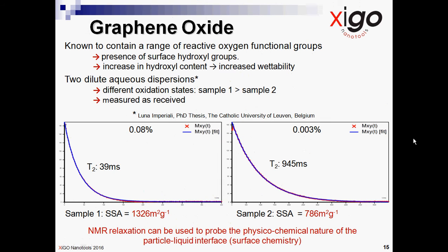Well, let's look at some graphene oxide. Graphene oxide sheets are readily obtained in large quantities from graphite. Moreover, the oxygen groups on the carbon backbone of the sheets make the sheets partially hydrophilic so that they absorb to a water surface, creating an extremely strong, flexible interfacial structure. Thanks to the mechanical integrity, it is possible to transfer large-scale films from the water surface directly onto suitable substrates.